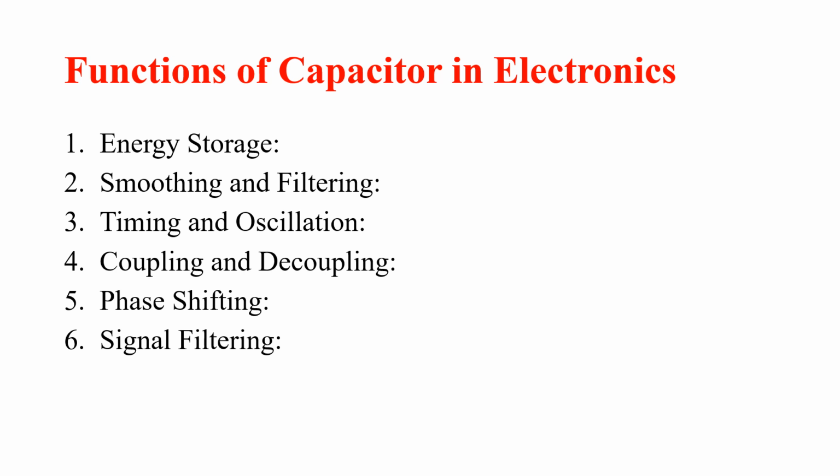Coupling and decoupling is another important application. Coupling capacitors allow AC signals to pass between stages of a circuit while blocking direct current from one stage to another stage. This is important in audio and radio frequency applications.